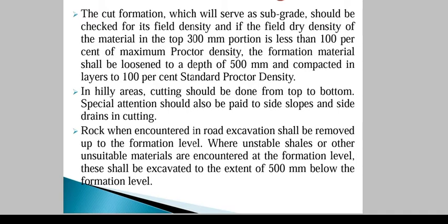Rock, when encountered in road excavation, shall be removed up to the formation level. Where unstable shales or other unsuitable material are encountered at formation level, it is extracted up to 500 mm below the formation level and recompacted.